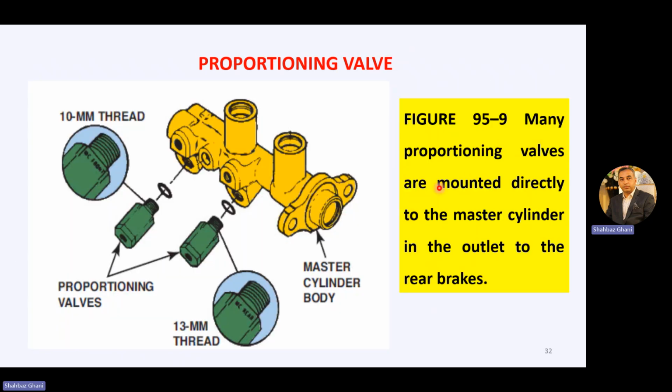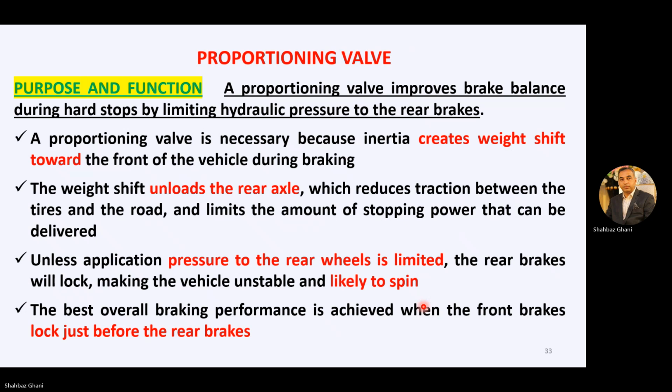Many proportioning valves are mounted directly to the master cylinder in the outlet of the rear brakes. What is a proportioning valve? Purpose and function. A proportioning valve improves brake balance during hard stops by limiting hydraulic pressure to the rear brakes.